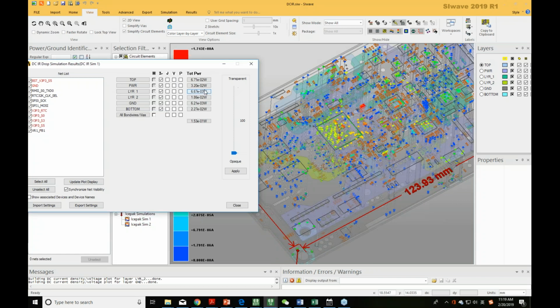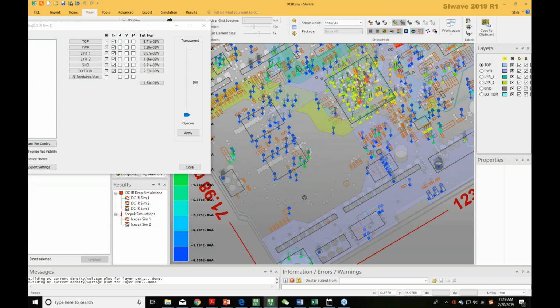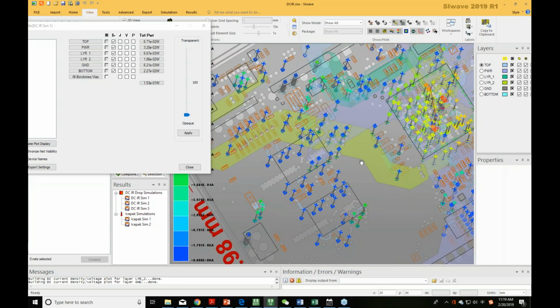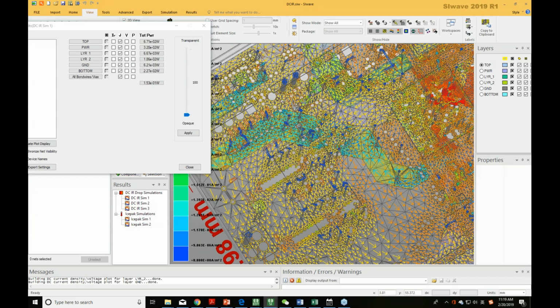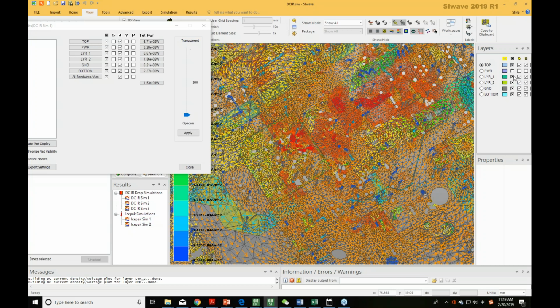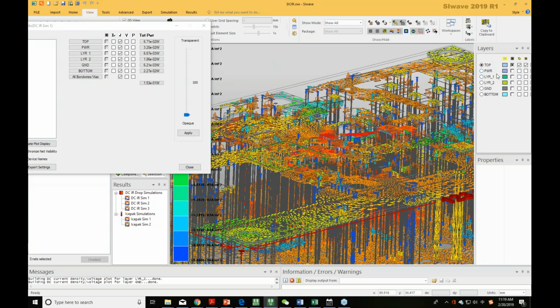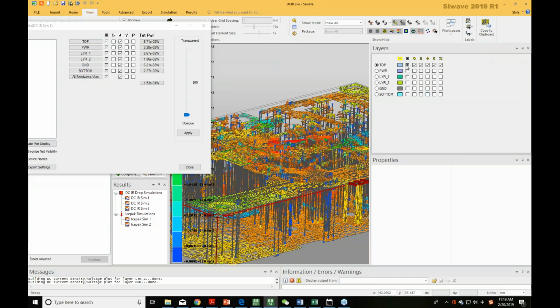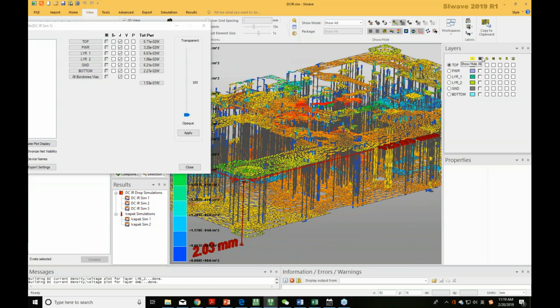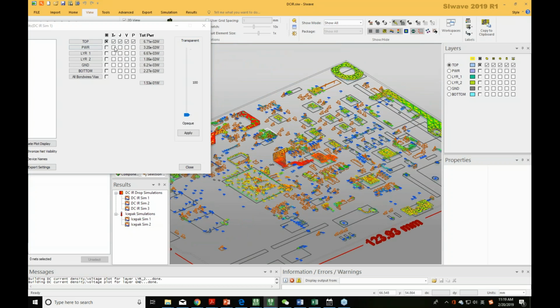So we check off some of the options. Just looking at first, we can look at the current through the vias. It tells you which via has a higher current, which via has a lower current. We can also check current density, where you can see how the current generally flows on every layer, to make it more friendly to our eyes. Okay, we check this layer. We uncheck all of them. Let's just do one layer. So we check this.